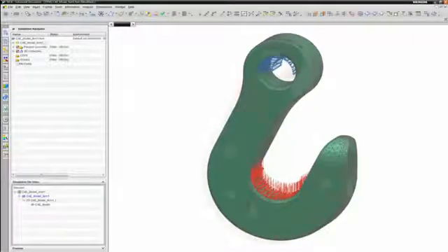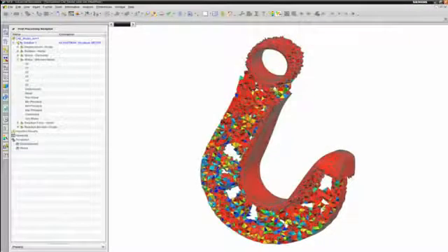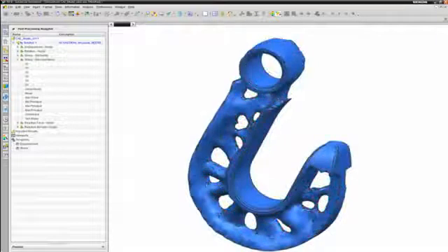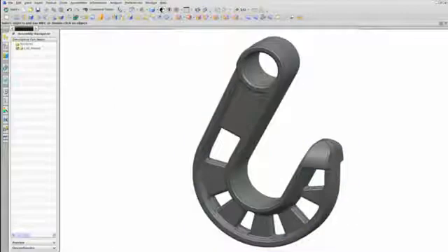Starting with an FE model of the design space, the solver computes a raw optimum conceptual design based on the loading conditions and your objectives. NX CAE seamlessly passes the raw conceptual results to CAD designers as geometry, which they can then further refine to create an optimum design right from the first try.